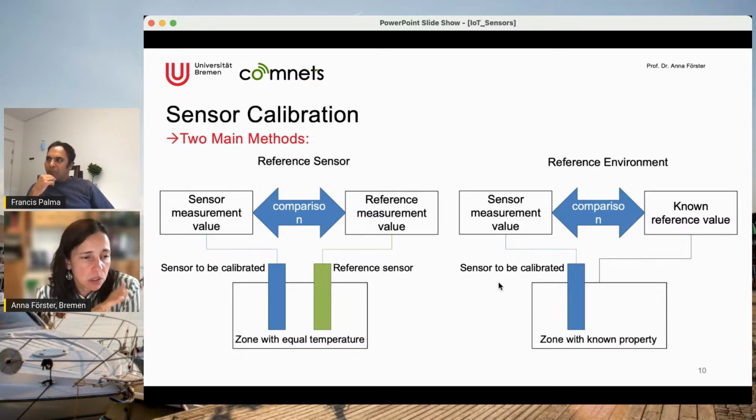Each component has its specifications: what is the input voltage, what is the tolerable input range? You have to consider those. If you don't, there is always a risk that your system will underperform, for example switch off, deliver wrong results, or do only half of the things you wanted. For example, the external memory might write some of the data, might not. On the other side, if you give it too much input voltage, you might burn your system completely.